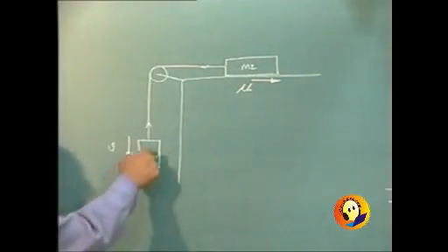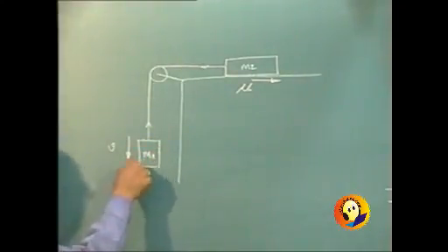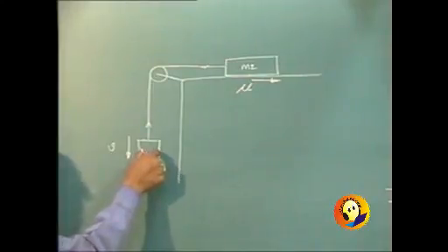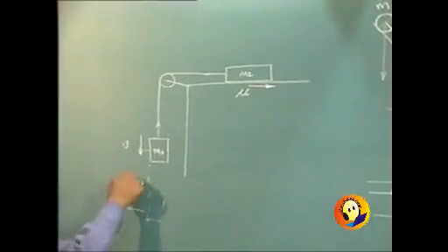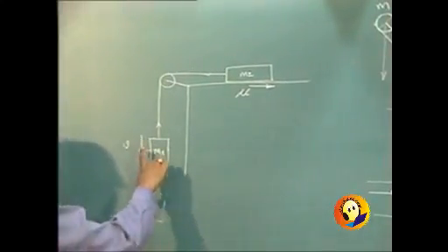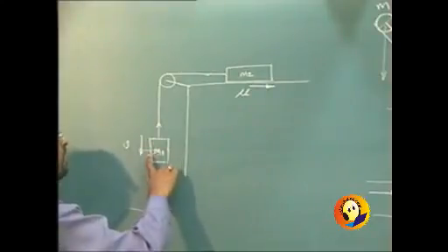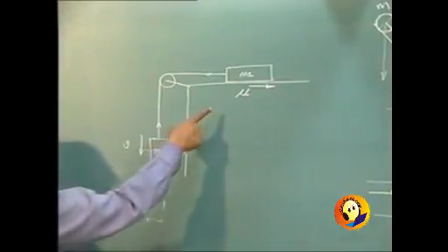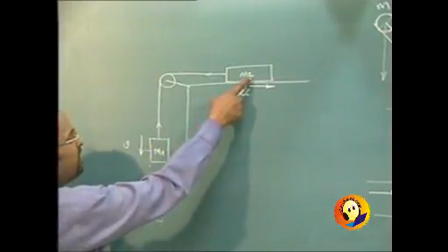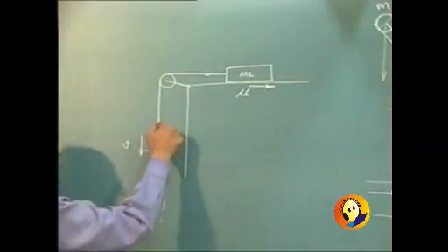And so the kinetic energy which we are imparting to mass m1, that particular kinetic energy will be lost fully, plus the potential energy loss which this particular mass m1 will be gaining. There is going to be change in the height also. So there is loss of kinetic energy, loss of potential energy, and both these energies will be lost in overcoming the frictional force. But when we talk of loss of kinetic energy, that loss of kinetic energy will be loss of kinetic energy of m2 as well as m1.